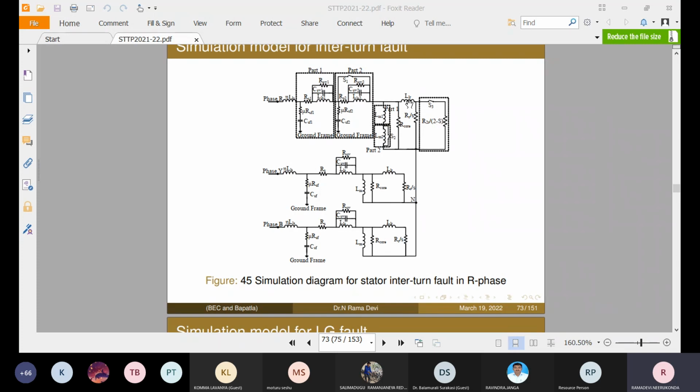But on the rotor side, we don't have any change, so we keep it as it is for the rotor leakage inductance. But the rotor resistance has a change. Whenever the fault happens, we represent the component corresponding to the unbalance in the system, which is indicated by the double revolving theory. According to that, the slip value changes: instead of RR by S, its value is RR by 2 minus S. This corresponds to the negative sequence component introduced in the system.